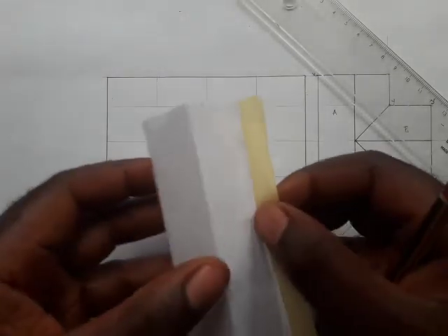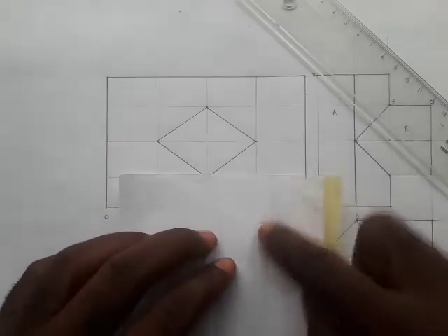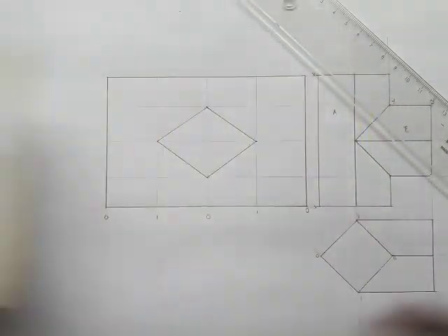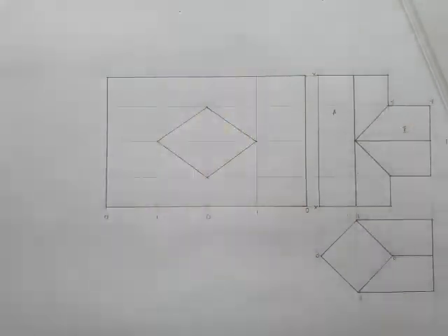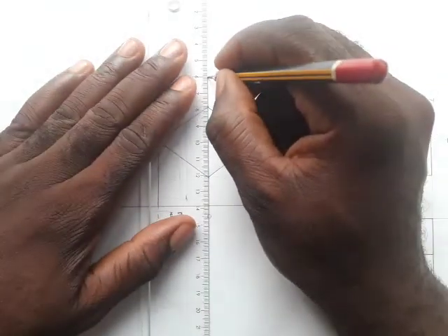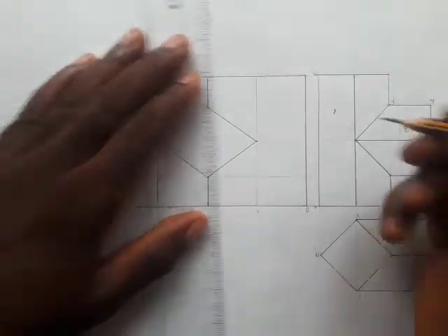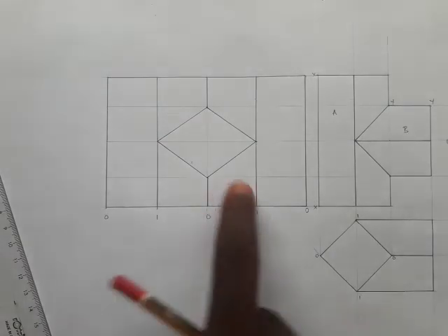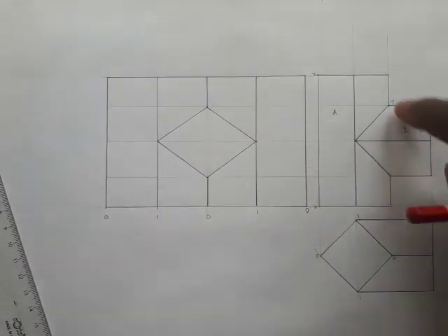this and this. Why? If this were to be the pipe, you know, we have developed it now. If you develop it, you open it up, actually you see these lines, this line, this line and this line, you can see that they are visible to you because they are actually edges, you understand? So you also have to draw them thick. So remember, this part has been cut off. All right, that's where the part that is making contact with this pipe. So you draw this line thick, you draw just from here thick, here thick, you draw this one thick. So this is the development of pipe A completed. Now let us develop pipe B.